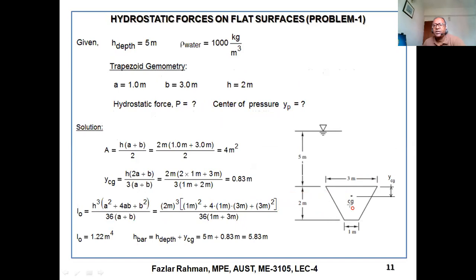Now, if you like to support this plate in the top and bottom, which one has to be stronger? Bottom has to be stronger because your resultant force is working through this point, which is close to the bottom.